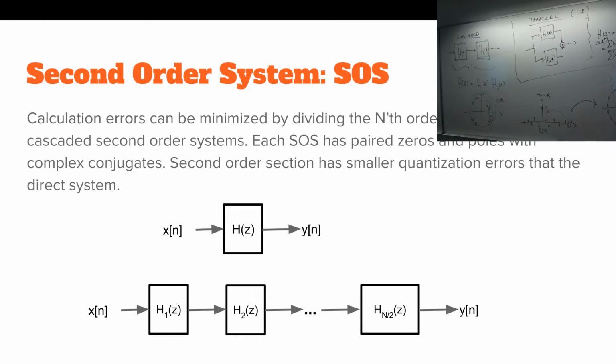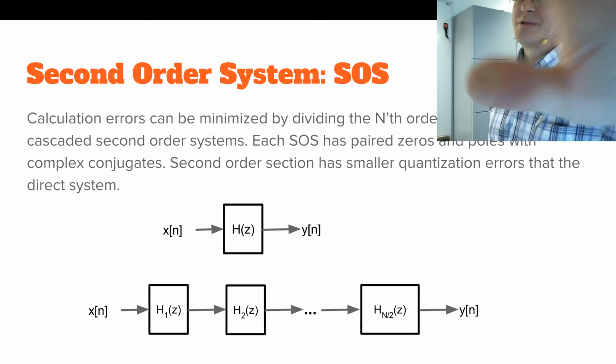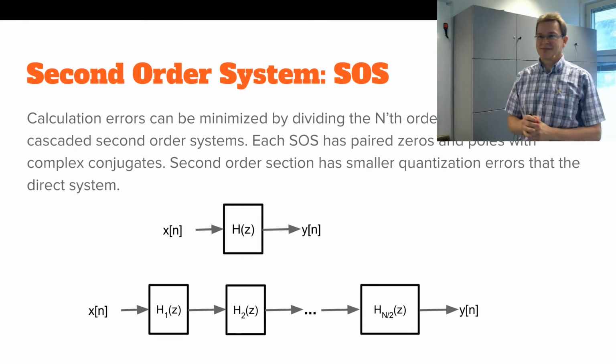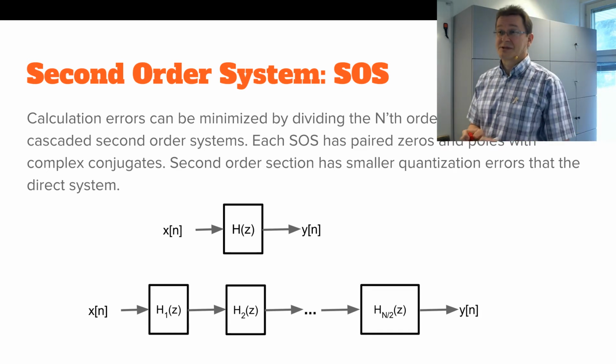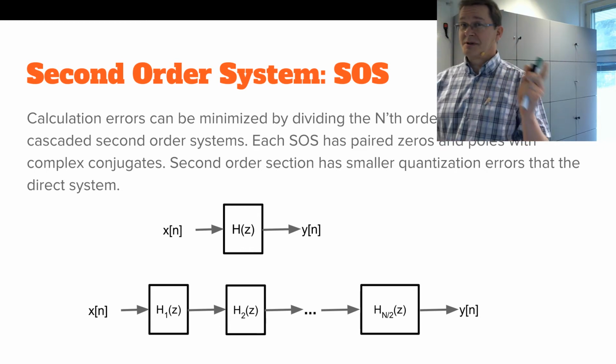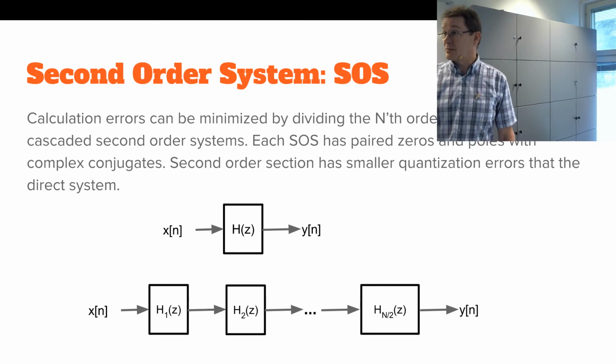Do you use any multiple accumulation units anymore if you have cascaded it? Yes, you can, but then it has to be designed for this kind of system, since, for example, those digital signal processors have some special registers, even if they have just a single MAC unit, which is an ancient processor though. But digital signal processors have multiple MAC units. So basically the parallel processing is perfect for this one.